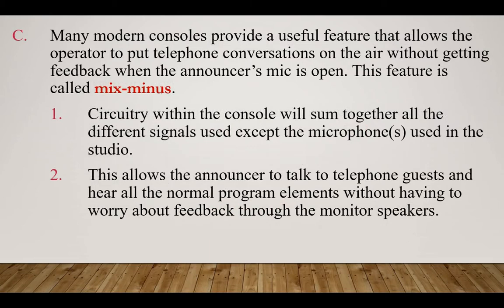Many modern consoles provide a useful feature that allows the operator to put telephone conversations on the air without getting feedback when the announcer's mic is open. And this feature is called a Mixminus. Now, I'm going to be honest with you. In any radio studio that I've worked in, I've not seen this feature used very well. There could be a number of reasons for that. But generally, the idea is that the board is going to be set up in such a way that you can have the telephone caller up and on while also having your microphone up and on, and you're not going to get any feedback issues.